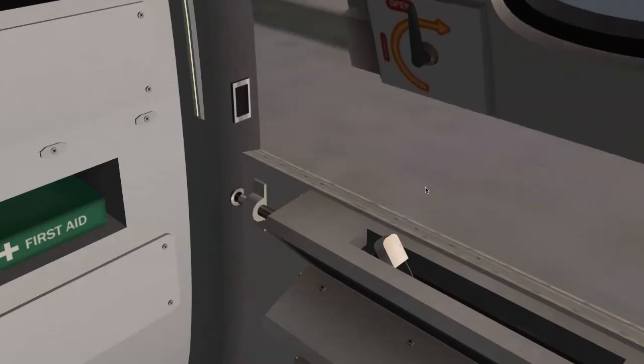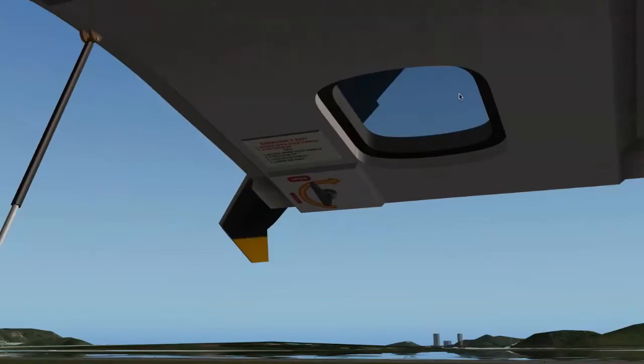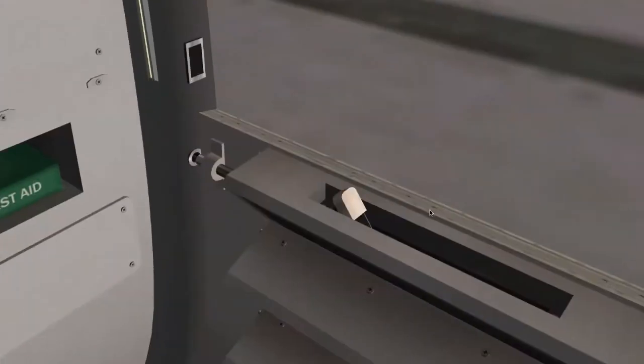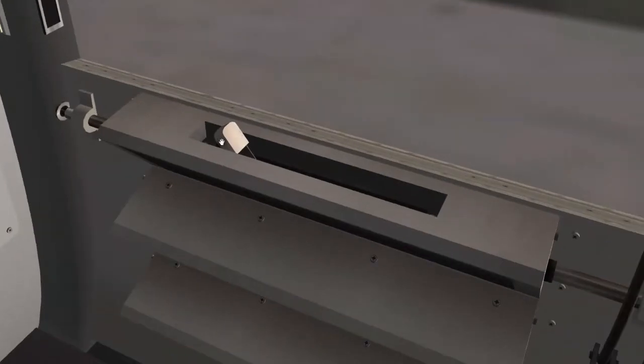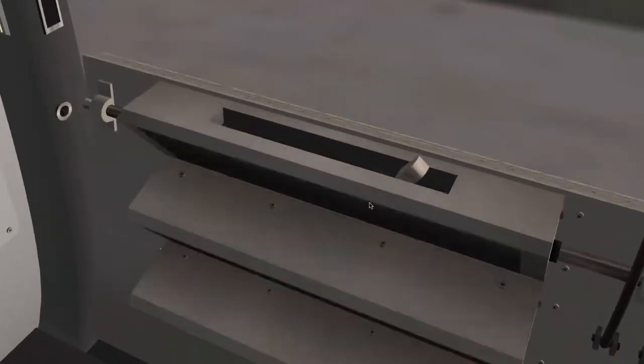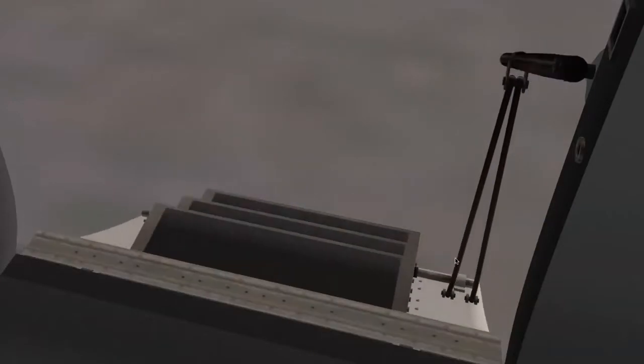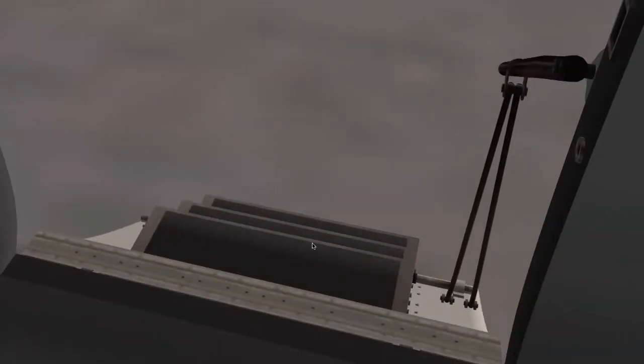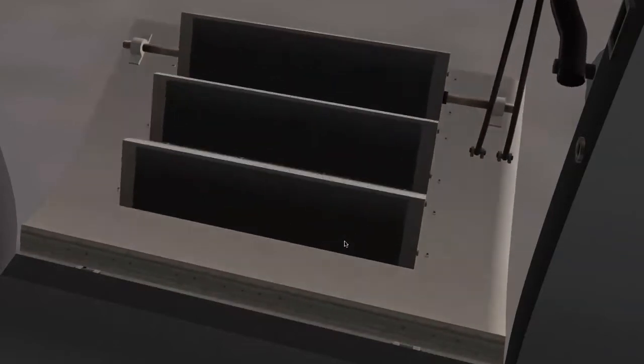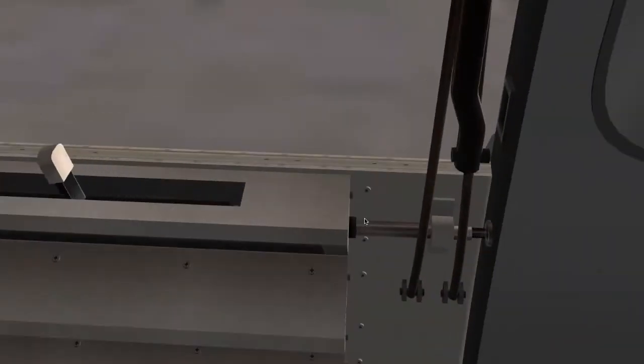It will open. Because the door is linked to the flap data reference, it requires power, because X-Plane, currently X-Plane 9 at least, thinks that all flaps require electricity. So if you've noticed that your doors don't open for some reason, it's most likely because the power is off.